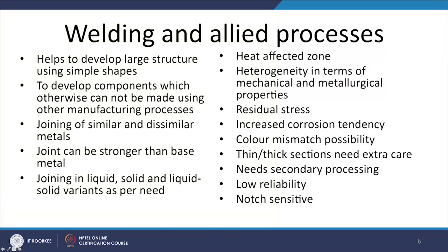Thin and thick sections need extra care in case of welding. Thick sections need multi-pass processing, which results in a very wide heat affected zone, while thin sections can lead to melt through or an increased distortion tendency of the thin sheets. The control of the weld pool becomes very difficult in case of thin sections.